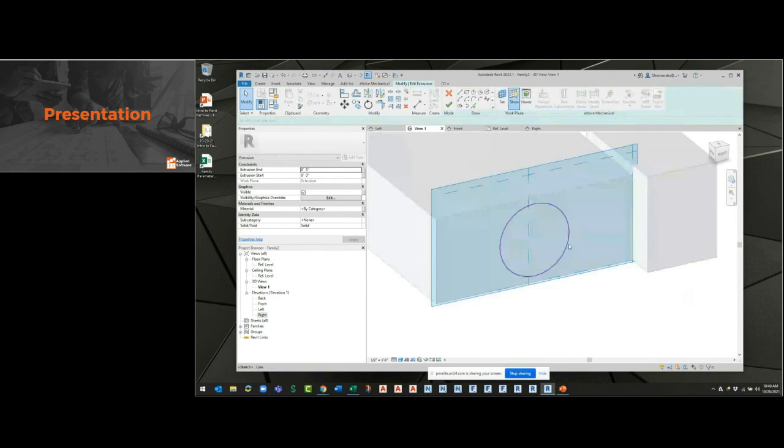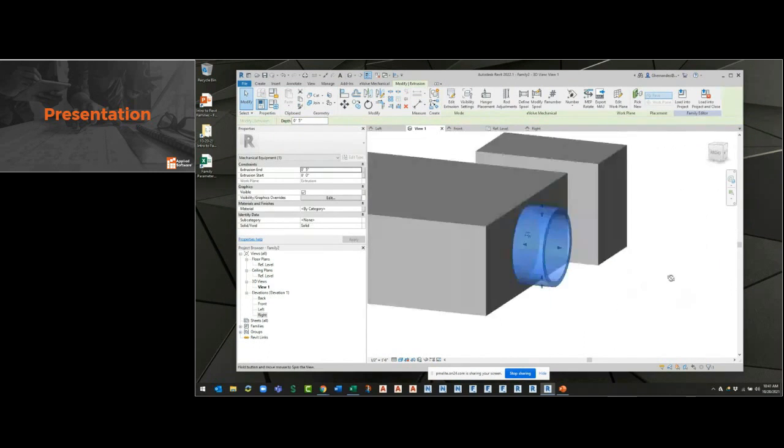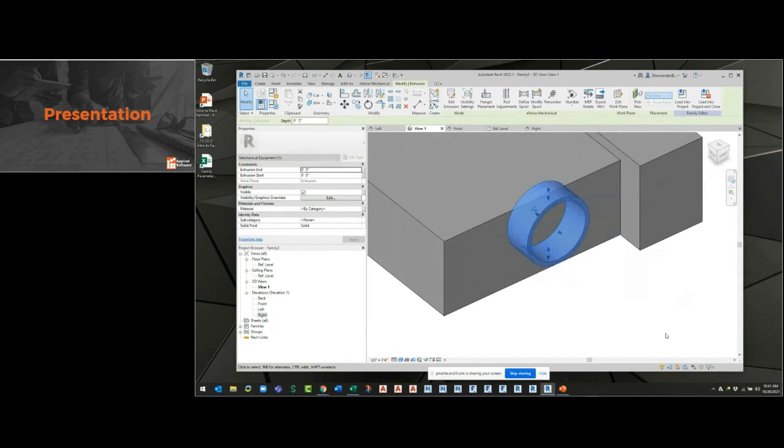What I should have done was, instead of making two pieces of geometry there, void and solid, I should have just created this in the sketch, because I could have a closed loop, two circles within each other, and that created the same exact situation without a void. So there's no void that comes along with it, right?